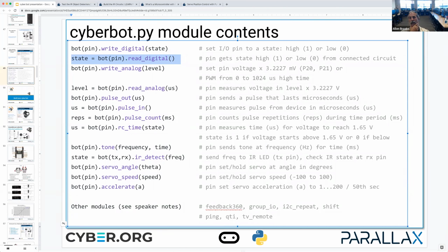I can store it as a variable if I wanted and just constantly monitor my variable. Yeah, that's much better. I didn't think about what the propeller was doing. The propeller has 2 different flavors of read digital, but my best guess is that I only did the flavor of read digital that makes the IO pin an input. Okay.